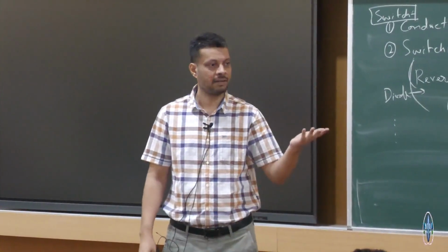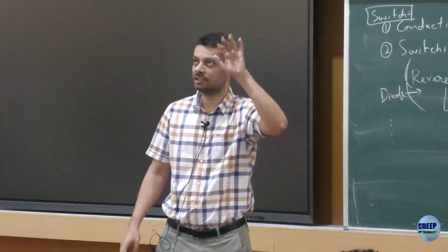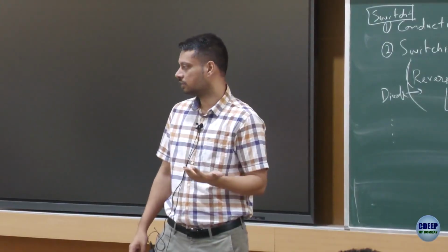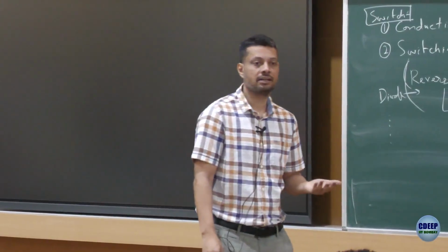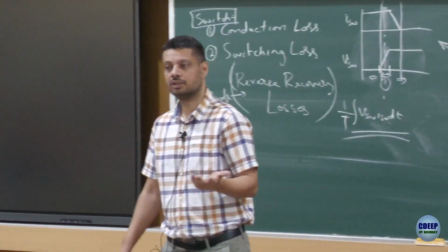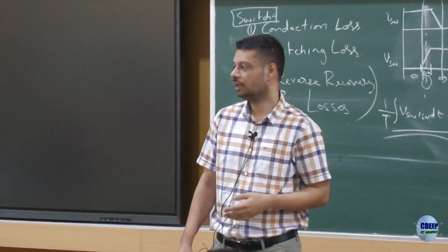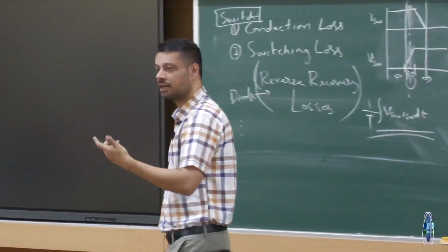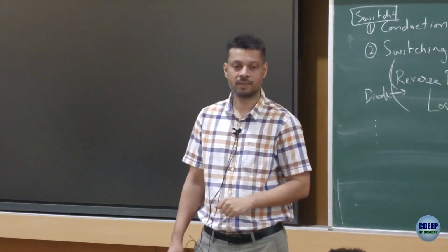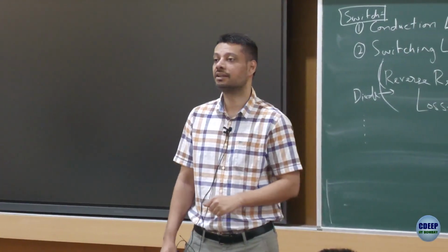And then if you see the buck converter, you had these two switches and you had an inductor, right. The inductor would also have losses. What kind of losses will be there in the inductor? So what are the other losses in the inductor? There is a conduction loss there also, right, I square R. The inductor would be made up of wires, so it will have a conduction loss. What else? What are the other losses in the inductor?